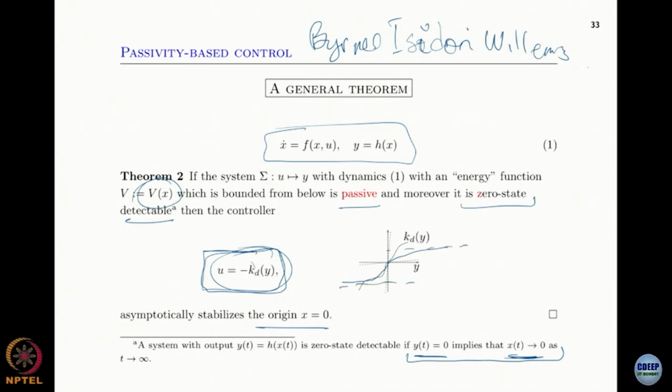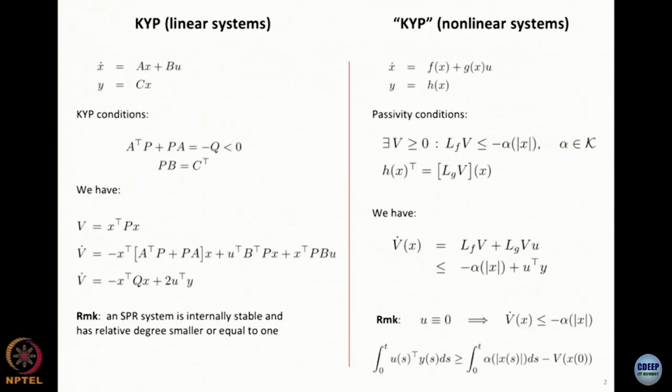Bounded there and there, and so on. So you can use many things. So let's see how passivity-based control works now. Now that we know the definitions of passivity and we know the Kalman-Yakubovich-Popov statement for linear systems and its equivalent version for nonlinear systems, again taken from Khalil.